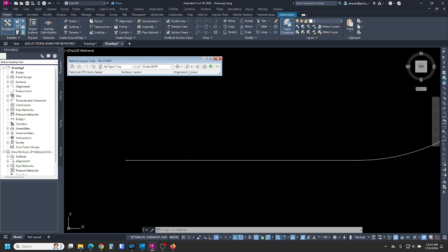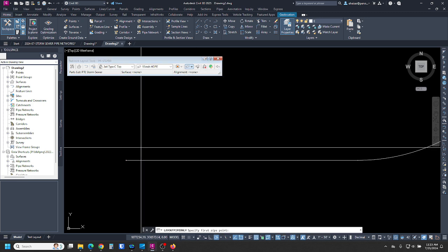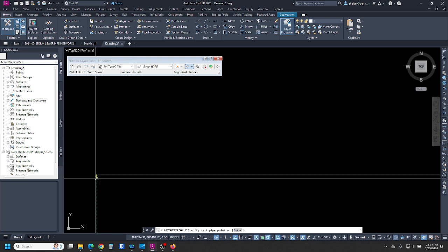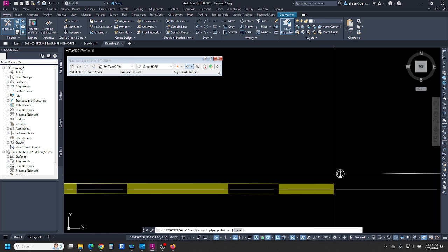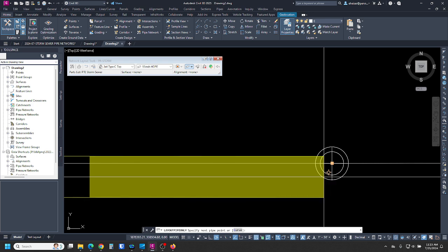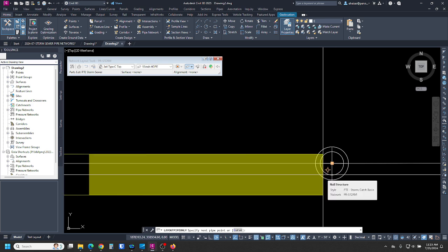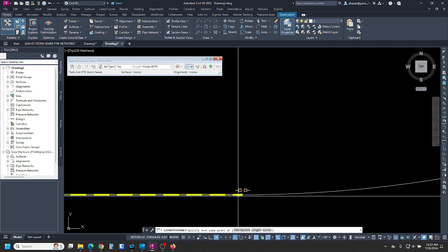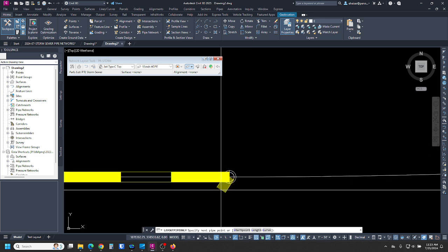So we're going to do 15-inch, pipes only. We're going to say this is the high end. We're going to draw our pipes from high to low like we would normally. When you're drawing, you'll get the connection interactive glyph that shows up at the end of that pipe. Looks like a crosshair. That's telling you that you're connecting. So I just connected there.